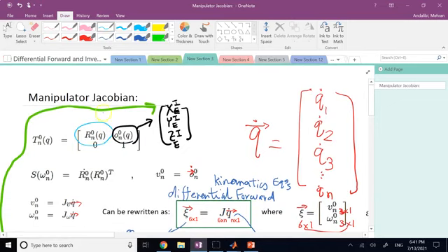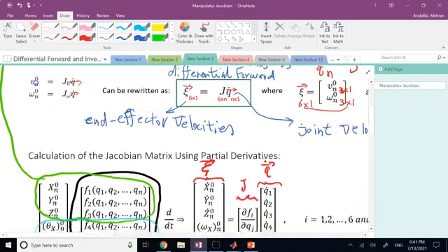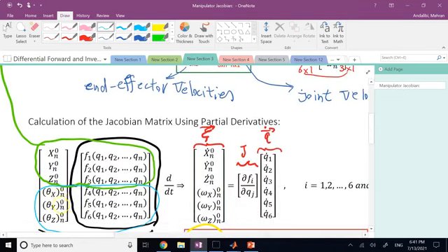As a matter of fact, most of the time this rotation matrix is written in terms of intrinsic rotations, which are rotations with respect to what? You're right, with respect to the current frame. These thetas are absolute. They are with respect to the fixed frame, the base frame. So these are the angles of one frame with respect to another, absolute angles.